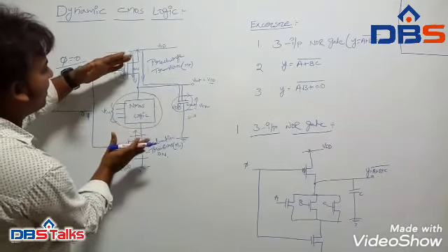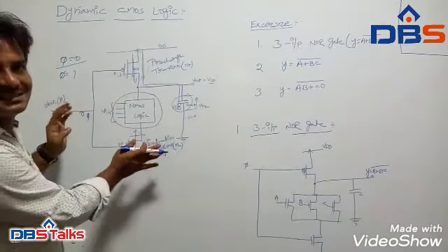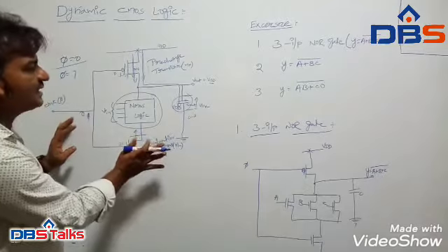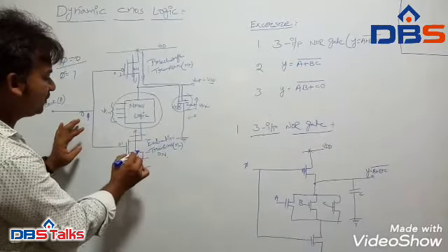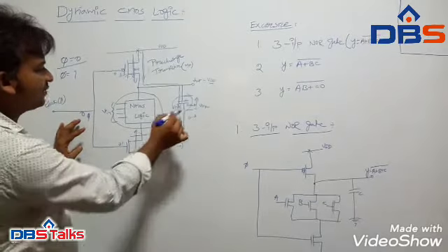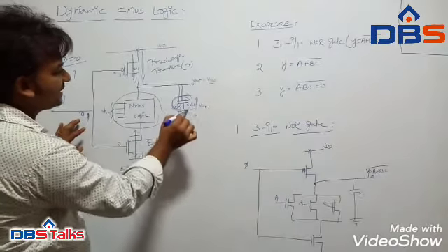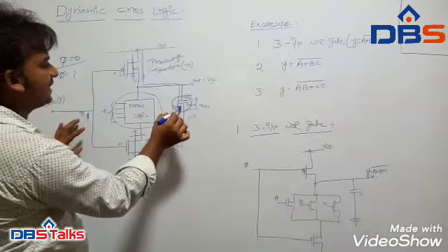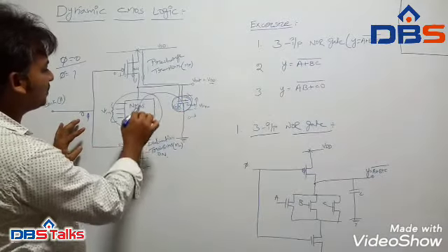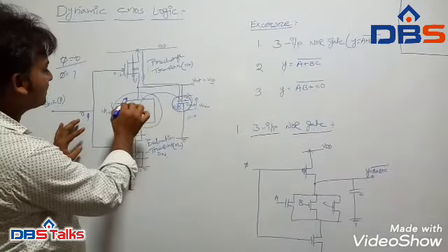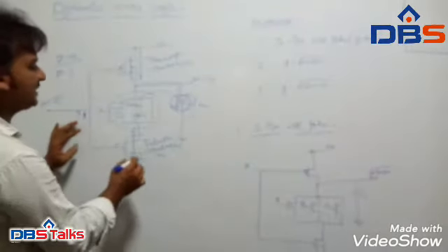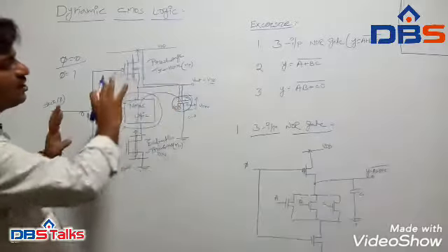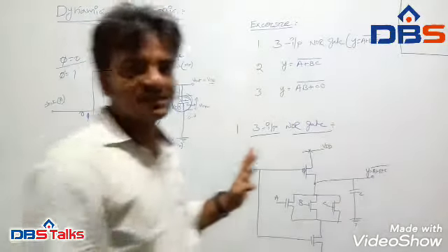be dependent on both the pre-charge transistor and the evaluation transistor. So during case 2 it will be on, so that whatever the voltage appeared across the transistor will be discharged through whatever the logic implemented within the NMOS logic by using the evaluation transistor. So this is the operation of dynamic CMOS